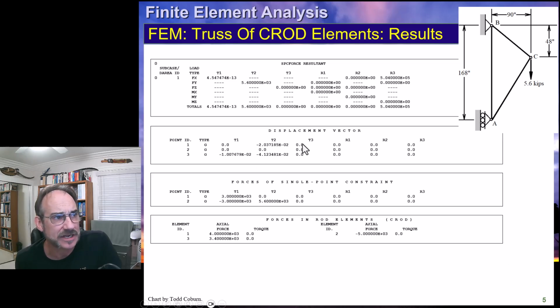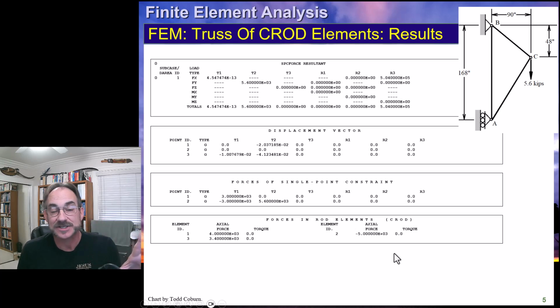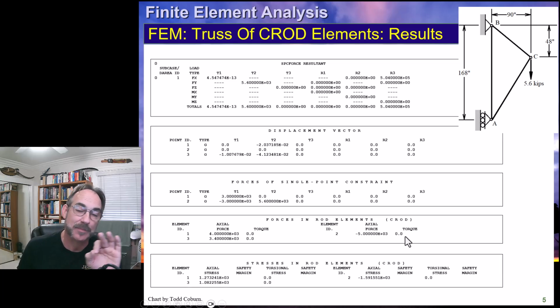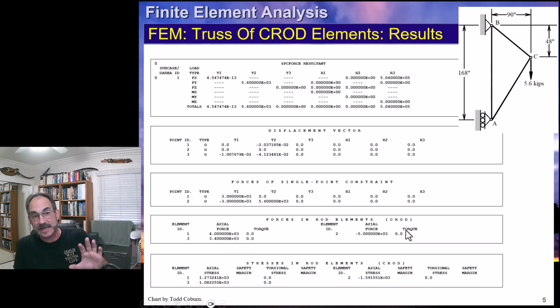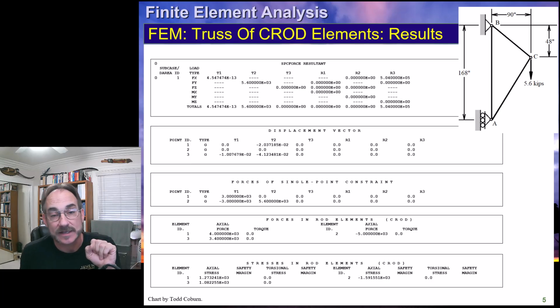You're not going to be able to check your displacements, but you can check your reactions using the forces of single point constraint. You can check your internal forces. This is a really good tool to make sure that your statics analysis is right, and also to make sure that your NASTRAN analysis is right. And once again, you can just check your answers against the book from your statics book if you're just an industry professional trying to get familiar with NASTRAN and wanting to practice so you understand how to do this quickly.